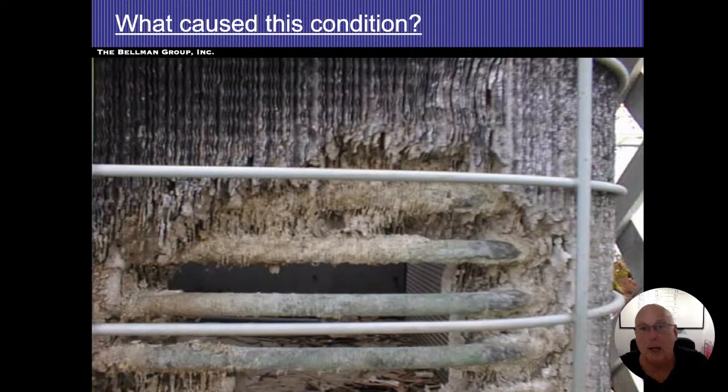All right. So just a couple of pictures and a few things that we end up seeing here. I like this picture because it shows the tubes that the refrigerant is actually running through, and it also has the fins that the air flows through. Now, this happens when a dog urinates on the air conditioning system. Those fins are very thin and fragile. A dog's urine is sometimes pretty acidic, so if they keep peeing on the air conditioner all the time, it wears away at the fins.